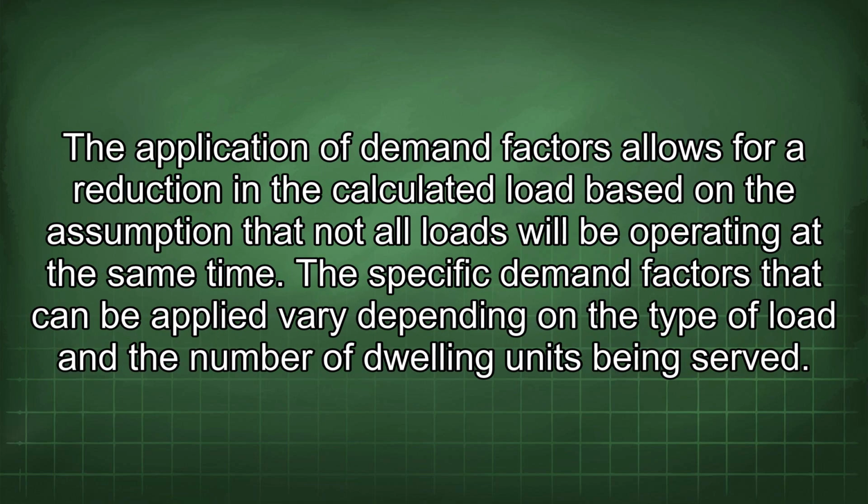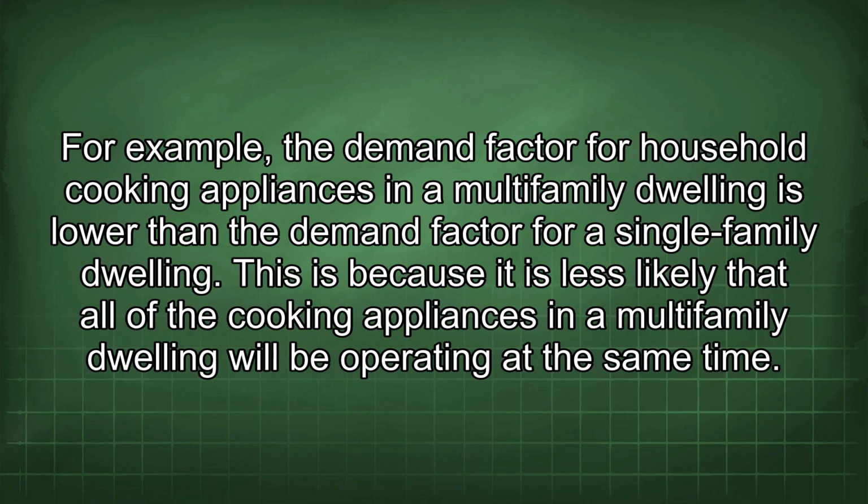The application of demand factors allows for a reduction in the calculated load based on the assumption that not all loads will be operating at the same time. The specific demand factors that can be applied vary depending on the type of load and the number of dwelling units being served. For example, the demand factor for household cooking appliances in a multifamily dwelling is lower than the demand factor for a single-family dwelling.